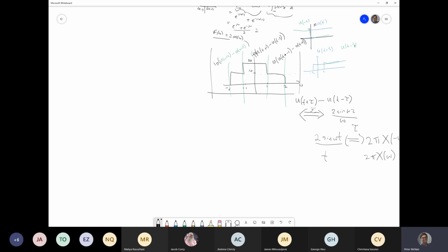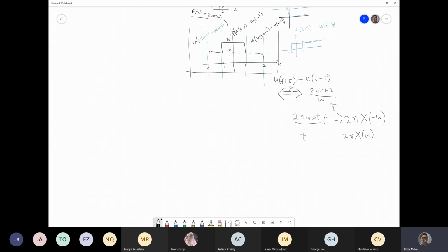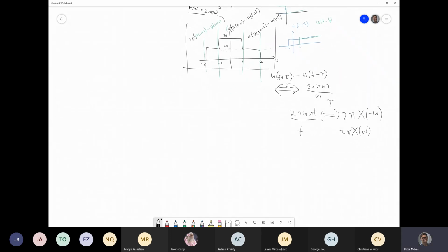Yeah. Okay. So in this case, we know that this is true, right? So we know that in the time domain, if you have a time signal that looks like this, where this is tau, that's minus tau and tau, then it has a frequency domain that's sort of a sinc.